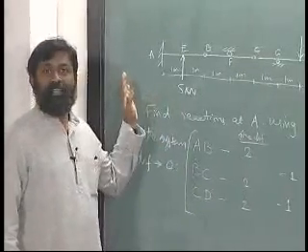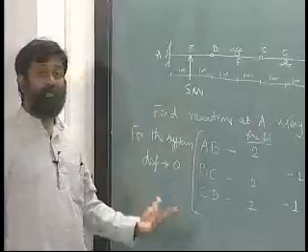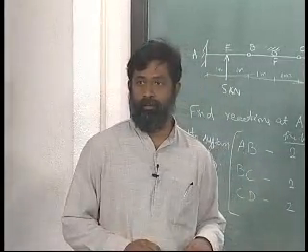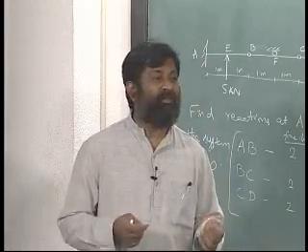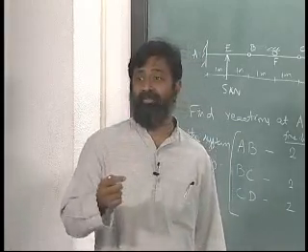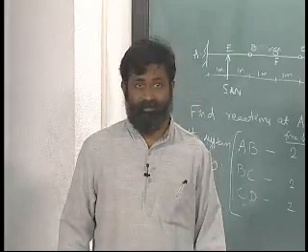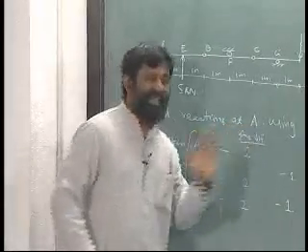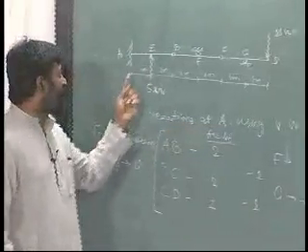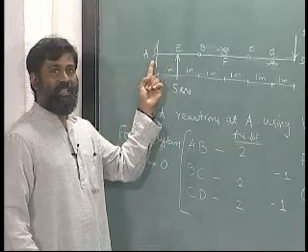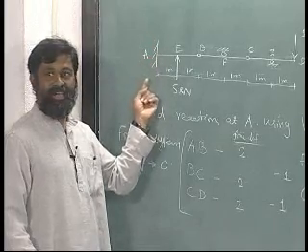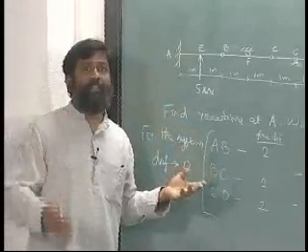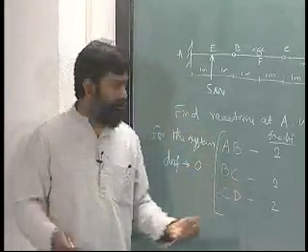Now, if it is a determinate system with a degree of freedom equal to 0, what do I know? I can't apply virtual work method directly. I have to release at least 1 degree of freedom in order to apply virtual work principle, alright. Well, what is asked is find the reactions at A, correct, which means what are the reactions here? There is a moment reaction and a vertical reaction. Okay, I may probably opt to release one of them and do the problem. Okay, so let us do that.